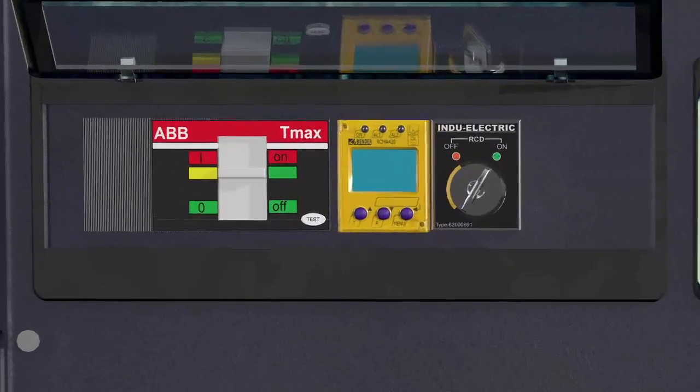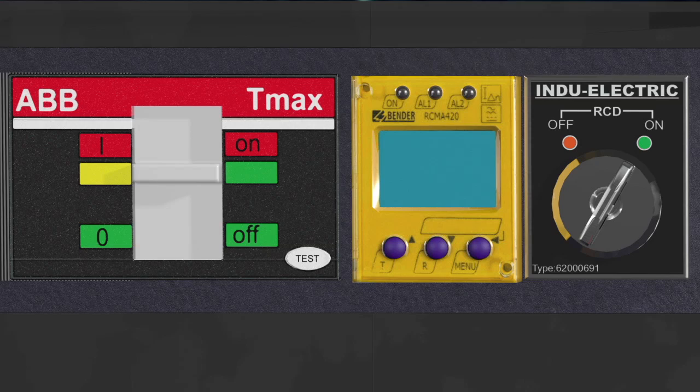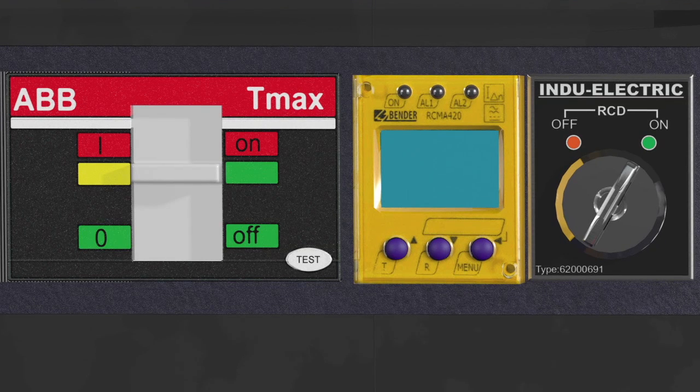The RCD cannot, however, distinguish between the different ground currents and will trip as soon as the sum of all leakage currents exceeds the tripping threshold. As we already mentioned, this is quite possible even under normal fault-free operating conditions. In stage systems, the leakage currents can amount to between 1 and 4% of the system's rated current, even in a fault-free installation. We hope that all the fundamental definitions have been understood well enough in order to proceed with the actual settings of the RCD.